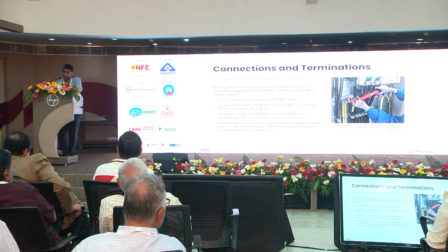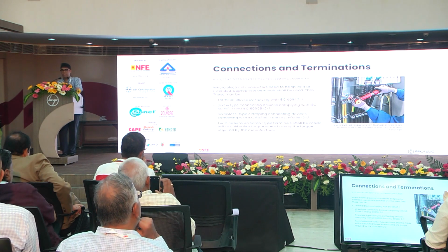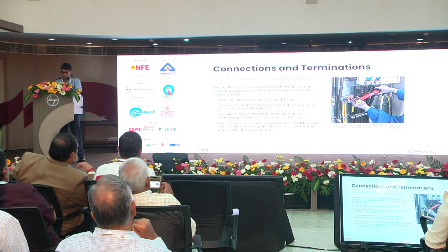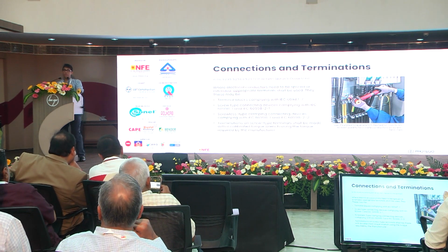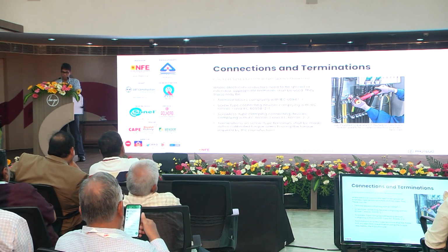And all these circuit breakers, right, even MCBs, even all these connecting devices will all say tightening torque 2 Newton meters, 1.2 Newton meters, whatever. Please follow these. Without doing this, all the money spent on your equipment is useless.